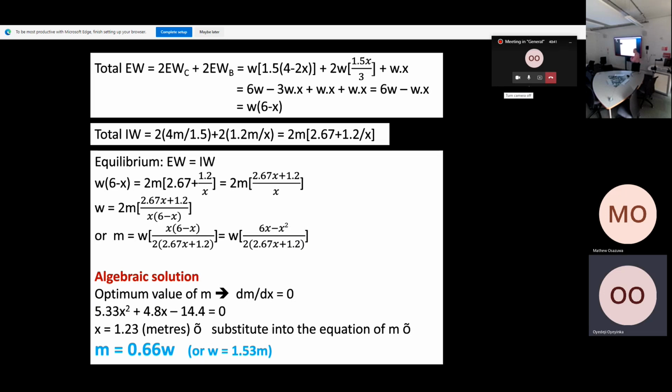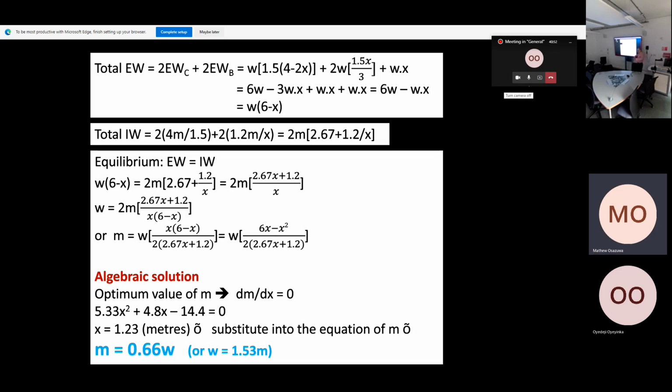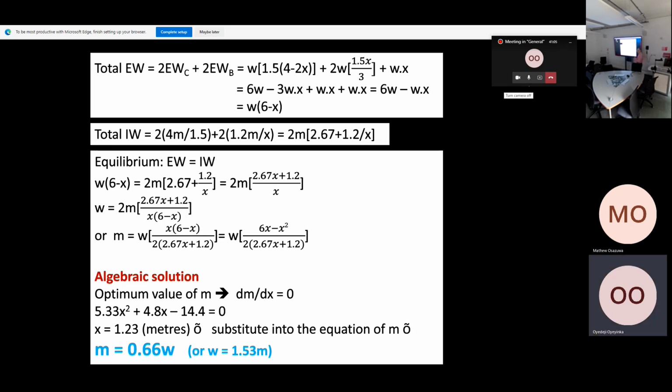The other alternative will be to test the slab in the lab. So you take your slab with the size, rest it on 4 edges, on 4 supports, and you load it with the UDL until it fails. When your slab fails, what do you know? You know the failure load. So when you know the collapse load, you use this equation, and it gives you M. Okay?